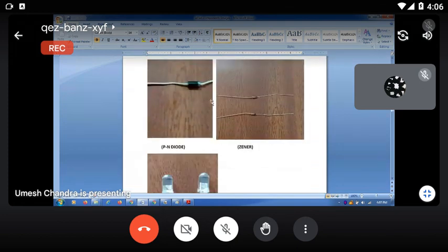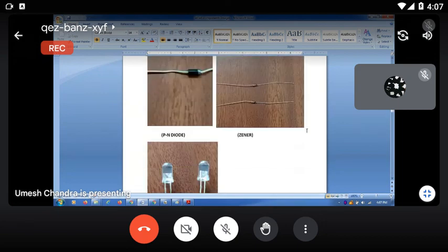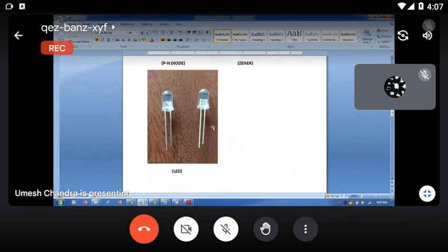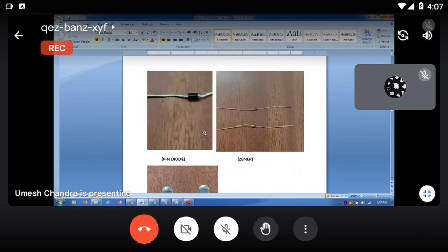And the next one is diode. That is PN junction diode, Zener, the different types of diodes: PN junction diode, Zener diode, LED, photodiode. Here there is no photodiode. Here are only 3 diodes: PN junction diode, Zener, and the last one is LED, the light emitting diode. For the PN junction diode, first you identify their positive and negative, P-type material and N-type material, or anode or cathode. Anode means positive and cathode means negative. Then how do you identify anode or cathode of the PN junction diode?